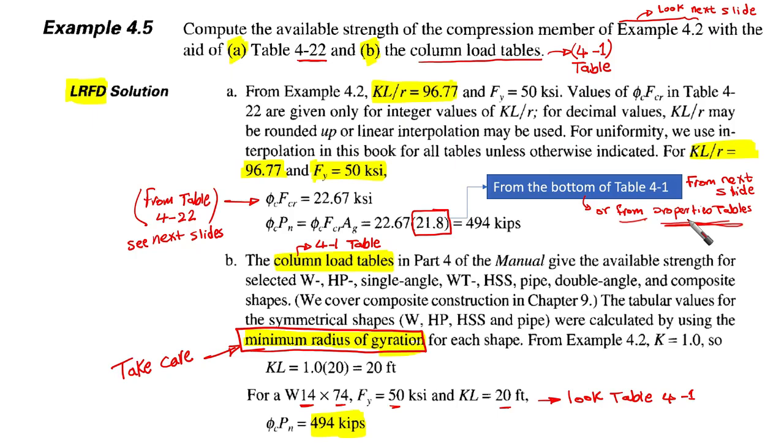So now this gives us how we are going to calculate. We obtain the value from the table and then multiply by the area gross to obtain the design strength. The design strength is 494. Now this is the available load after obtaining it from the table.